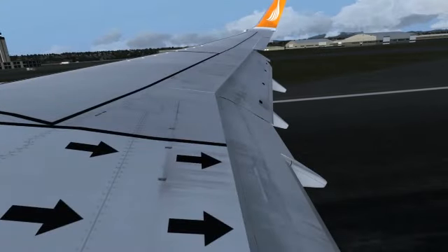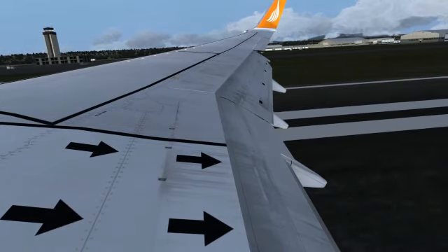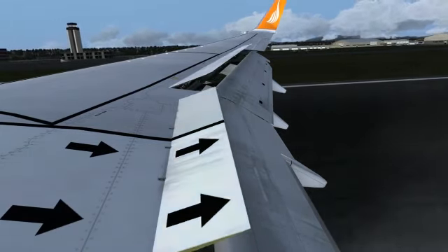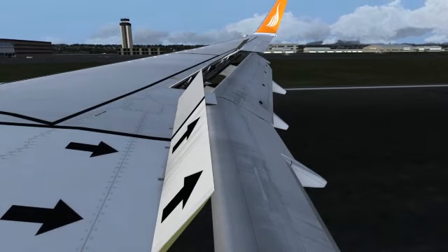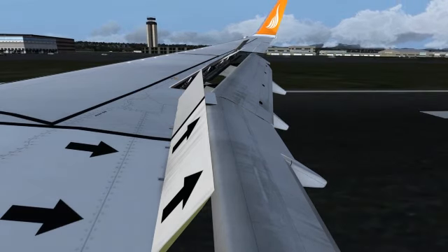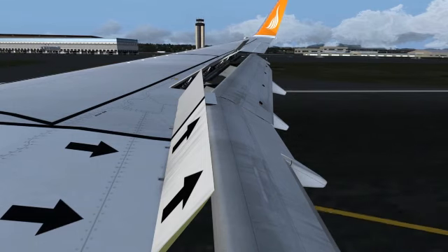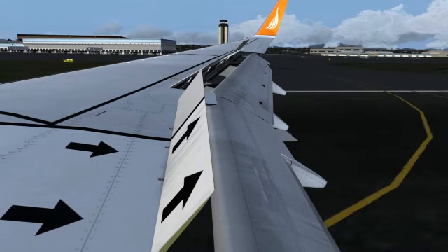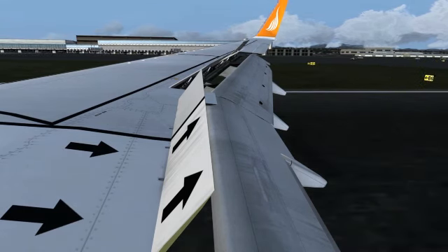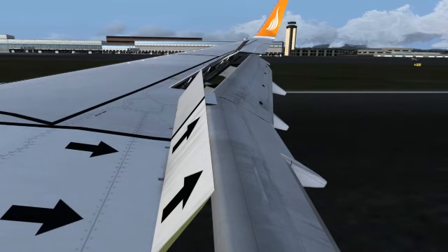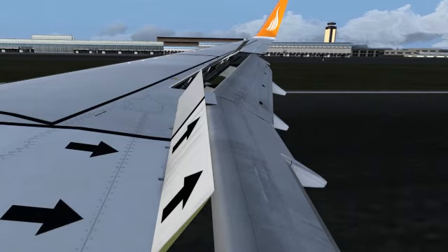When the aircraft is on ground, the spoilers have the following function. As a rule of thumb, the speed at which an aircraft touches down during landing is a few knots higher than the speed at which it would have taken off. This means that when the aircraft touches down, there's still a little bit of available lift in the wings. For this reason, spoilers deploy upon touchdown in order to completely destroy the excess lift and allow for the landing gear to have better adherence to the runway. This allows the wheel brakes to perform better and therefore reduce the stopping distance of the aircraft.